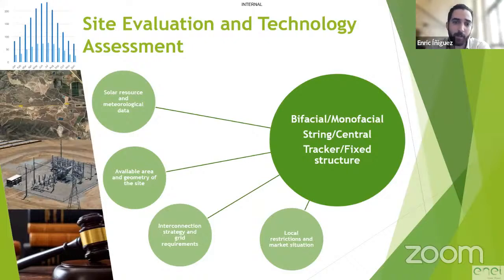My selection of tracker or fixed will come from the topography analysis of the site and the amount of power I want to install in the plot. Also, it is very important to know the legal frame of the region, as many of the administrations have particular sets of rules and constraints when it comes to developing PV parks. So at this stage, it's important not to hurry and to understand as much as you can. As I said, the context is vital. There is no such a thing as a preset PV park.